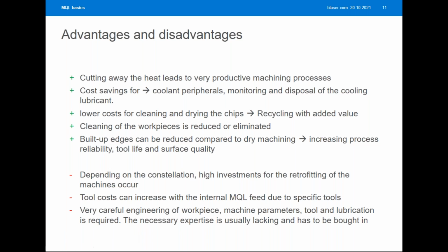And there is a lot of effort needed to get the processes work out. So a lot of engineering of workpiece, machine parameters, tool lubrication and everything. So this takes up a lot of time, and that's also why MQL is mainly seen in the large scale production.